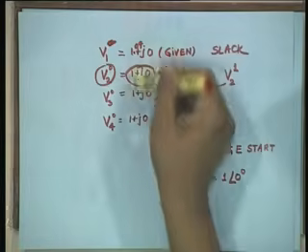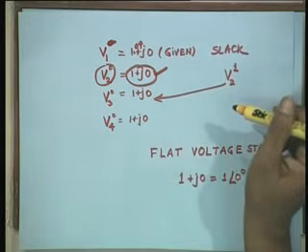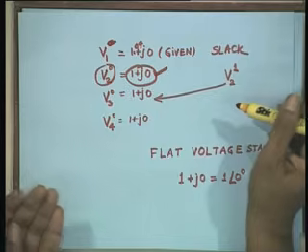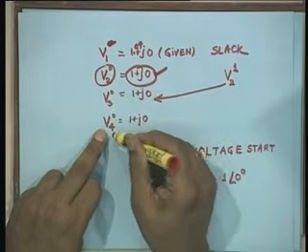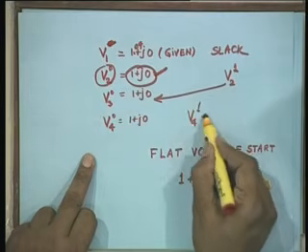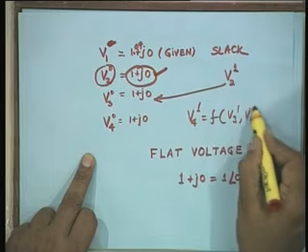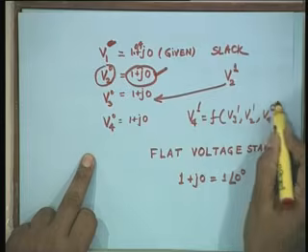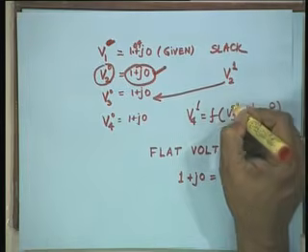Instead of using the earlier solution vector, we immediately update it with the latest values of voltage. When you go for V3(0), we immediately use V2(1). When you calculate V4(1), then you should use V3(1), V2(1) and V4(0). So, immediately update rather than using the 0 values here.